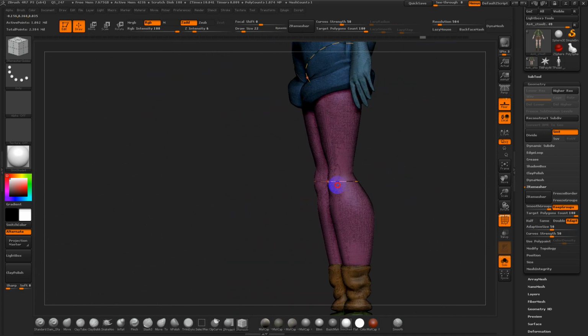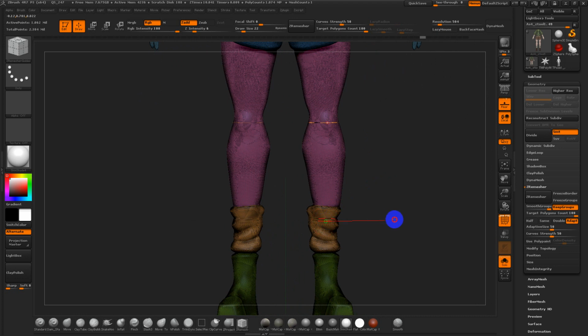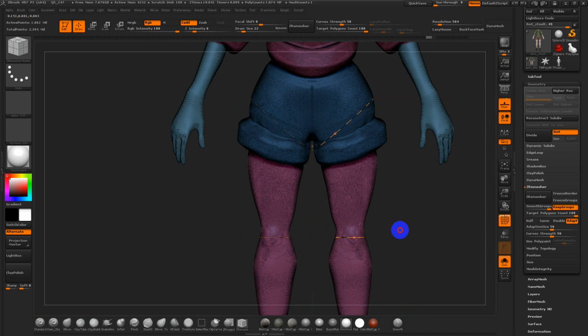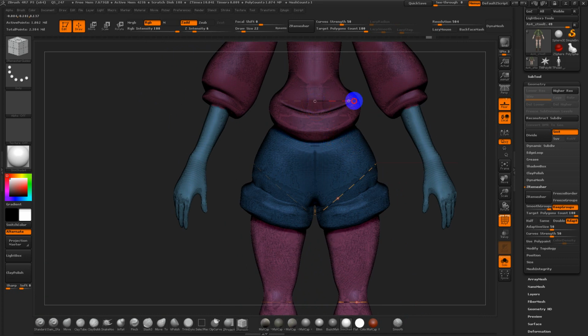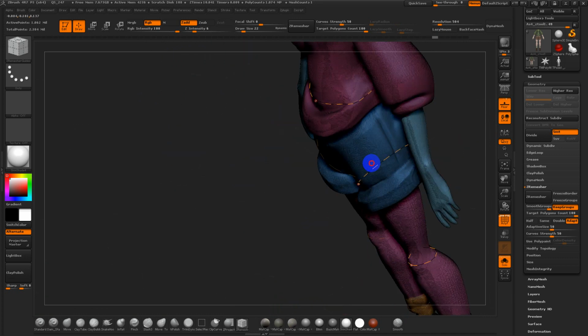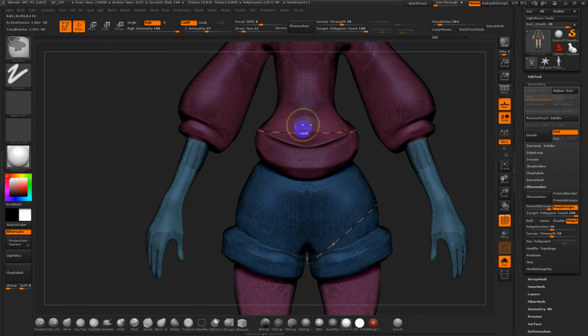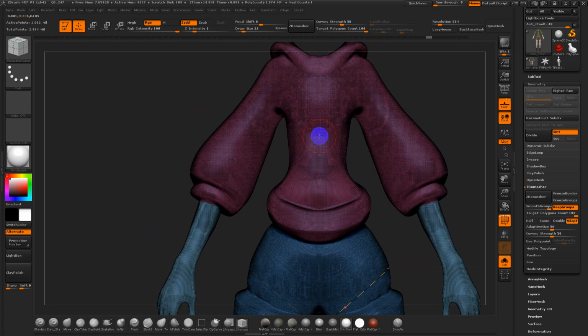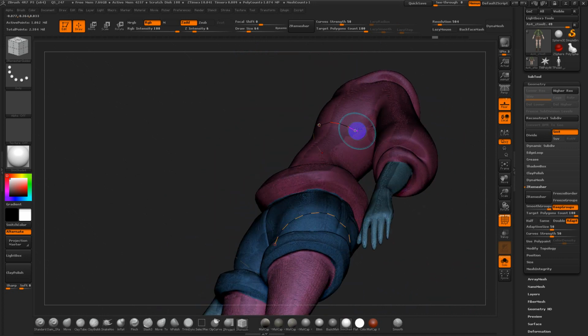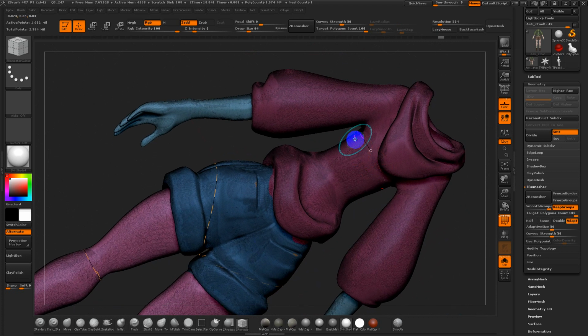To get a loop that jumps around the whole mesh, you click and drag and then hold Shift, and it does an auto loop around the mesh. It's not always clean when you're doing a central one, because if I do it here, I'm potentially going to get a duplicate loop since I'm working in symmetry, and sometimes it's hard to align it. So I often just draw it manually, maybe tracing along certain edges. And remember, if you draw a loop and it stops, we can pick it up. If you hover near the end point, it'll turn green, and you can keep drawing your way through to the back.